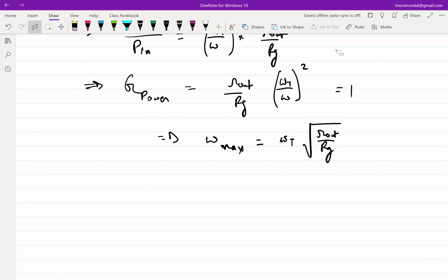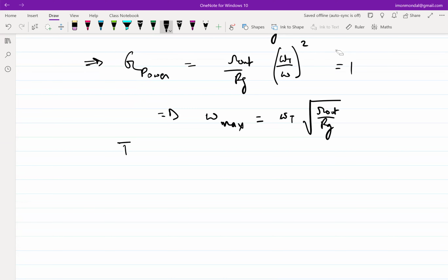So if you have a common source amplifier, let's say with a current source bias or something. The bias is not important. I'm only focusing on the MOSFET. If I have to get a lot of power at the output, this node will swing. When it swings, what can you comment on as far as the breakdown voltage of the MOSFET? If the swing is more, the MOS is being pushed towards breakdown, right?